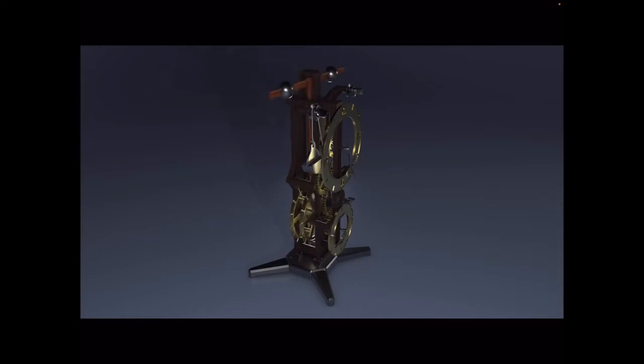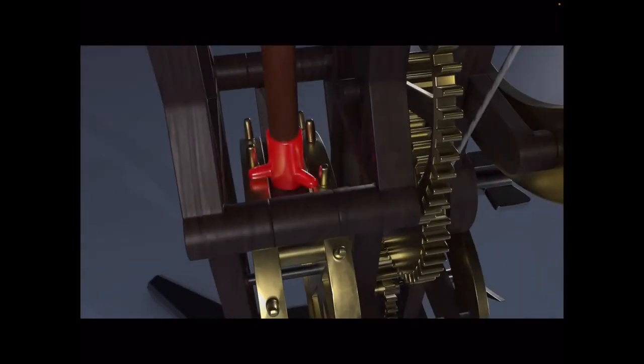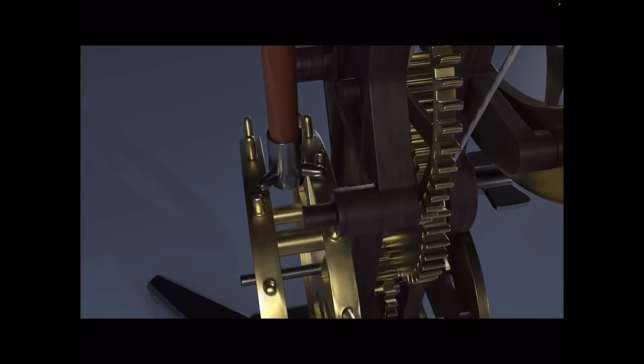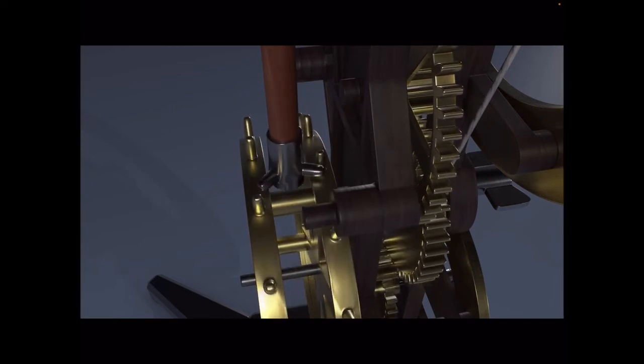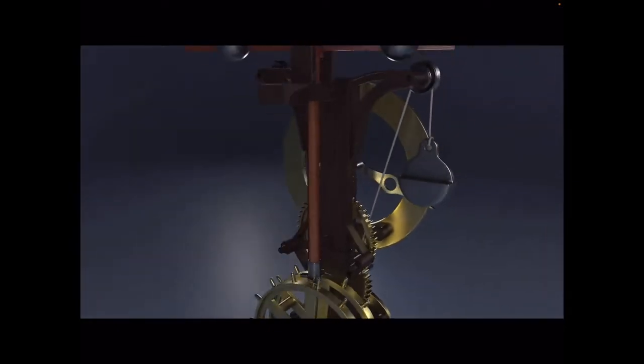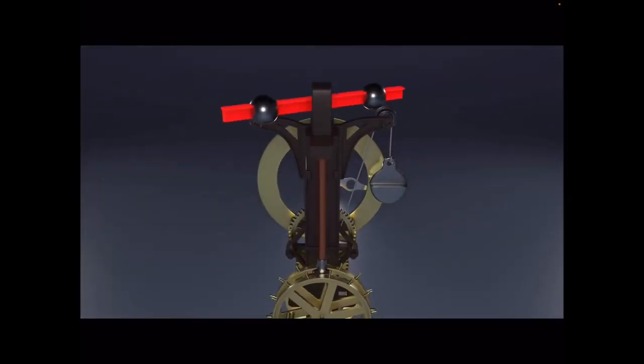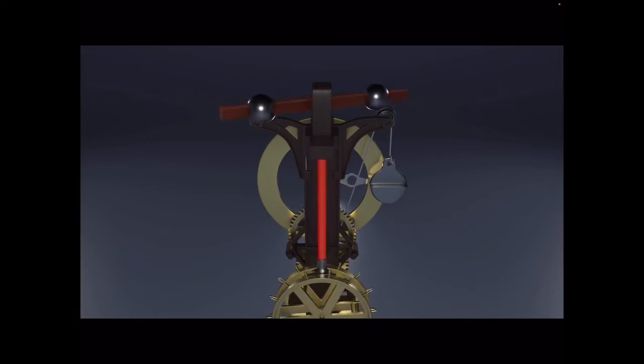The energy stored in the drive wheel needs to be released in a controlled manner, or else it will be released all at once. The escapement provides that control. The escapement acts like a switch to meter the release of stored energy through the escape wheel. As the escape wheel turns, it comes into contact with the pellet teeth of the escapement, which stop the forward rotation of the escape wheel. This is done in synchronization with the movement of the pendulum, which in this clock is attached to the escapement by the shaft.